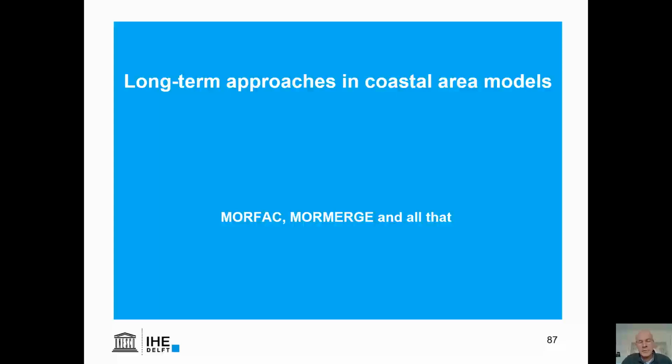Okay, we've figured out how to do the hydrodynamics and the sediment transport in a two-dimensional model now. But now let's see how we can turn this kind of simulations into a medium or long-term morphological model. We're going to be talking about different approaches, including MORFAC and MorMerge and all that.